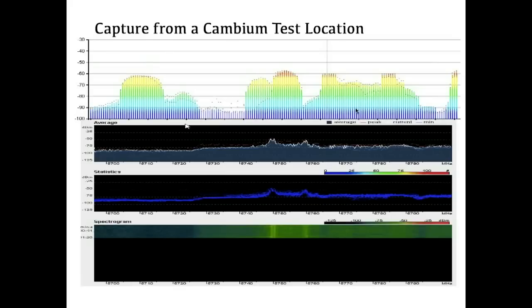My next slide is actually a sample picture from a Cambium Networks test location that shows the problem of crowded spectrum in 5 gigahertz. I've seen many worse, where the spectrum is crowded in the entire 5.2 to 5.7 band. So the message here is that the channels you do find every now and then that are clean and you're trying to operate on, it's precious to you.